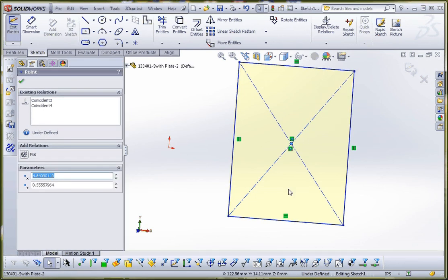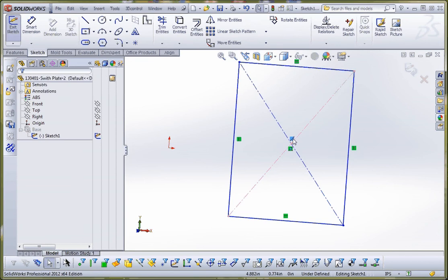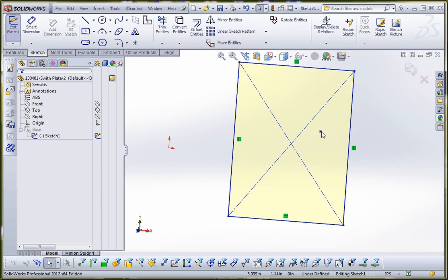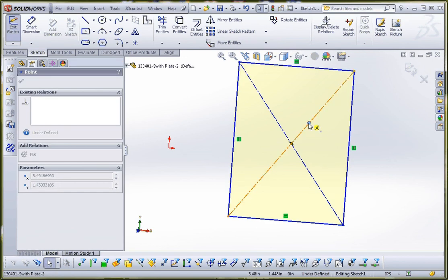If you click on that line, you can see, or click in the sketch relationship down here. It's associated with that point and the center lines there. And this sketch relationship also involves a coincident relationship between that center line and that point. So if we were to delete these, you'll notice that the point actually comes off those lines. So we're going to take that point, and if you approach another line in here, it doesn't have to be the center lines, it's going to establish a relationship here.